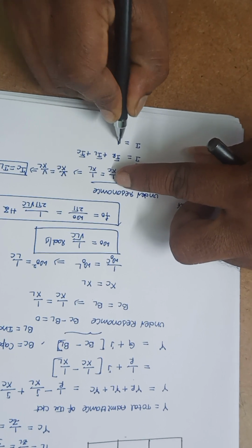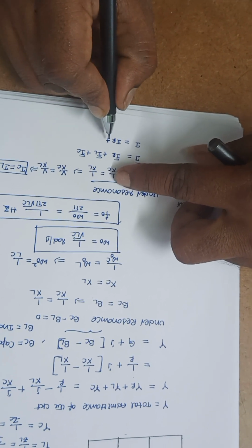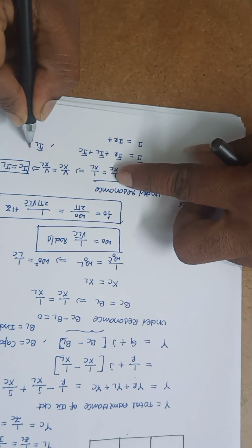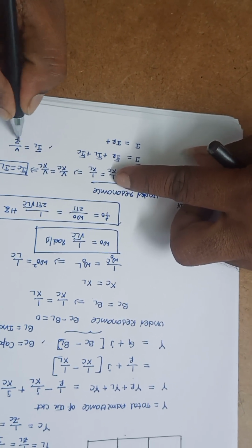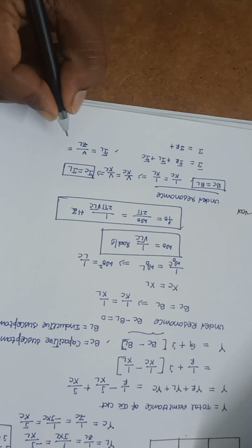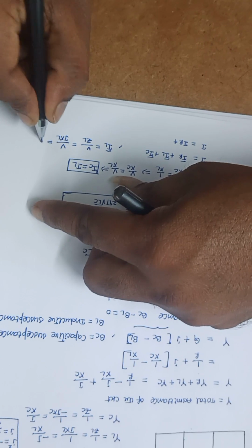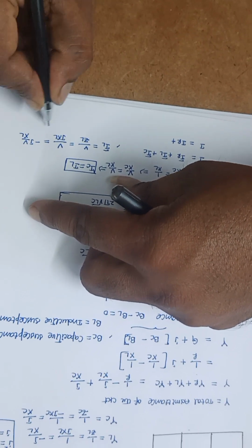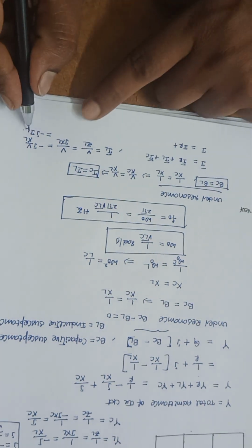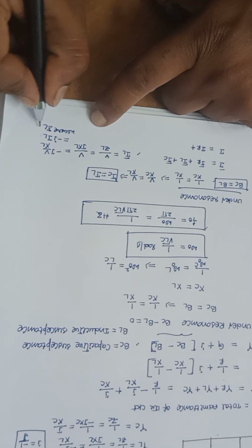So I is equal to IR plus this IL bar. IL bar is actually V divided by ZL, where ZL is the impedance of this coil, J into XL. That is equal to minus J into V by XL. So I can rewrite this as minus J into IL, where IL is the magnitude, IL is equal to V by XL.